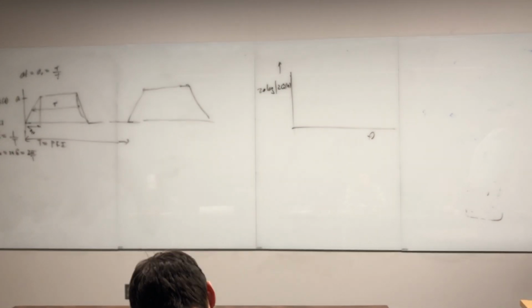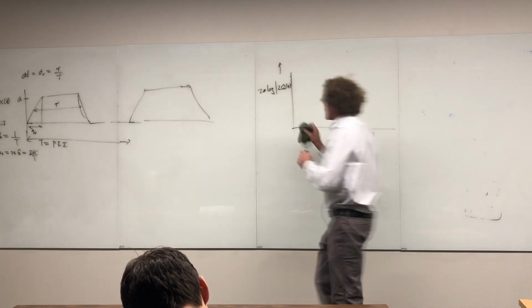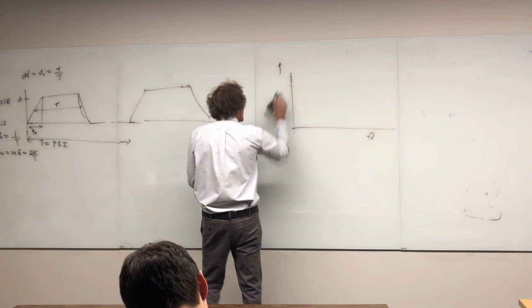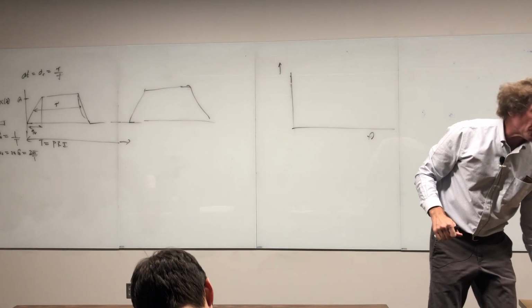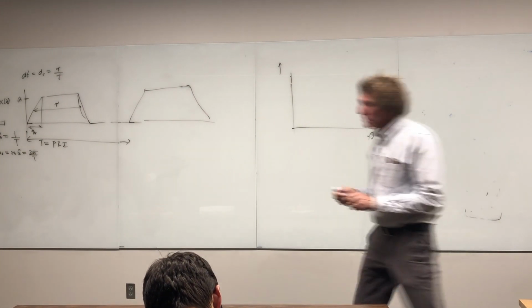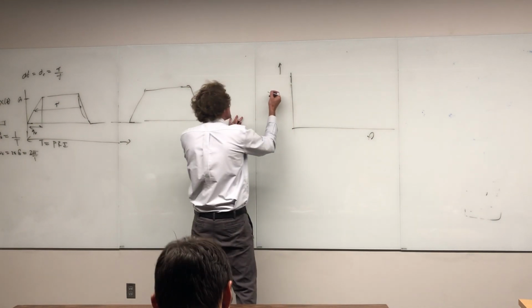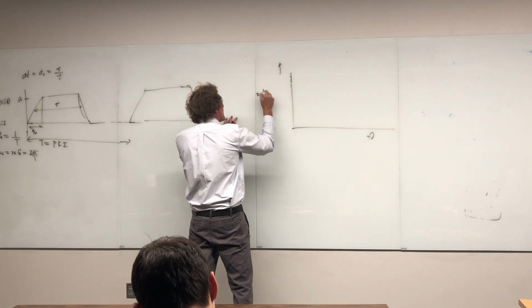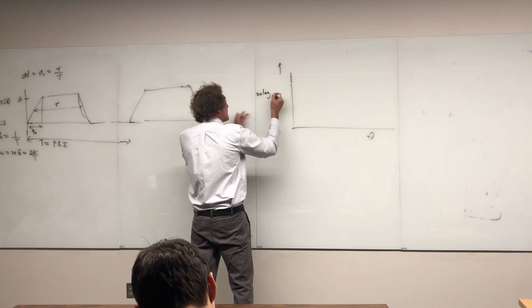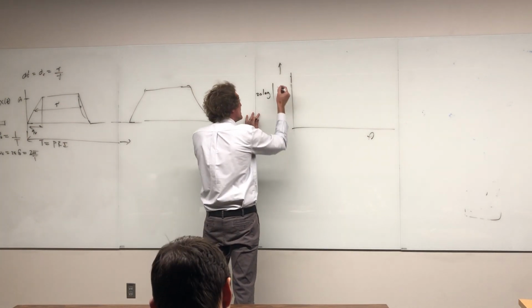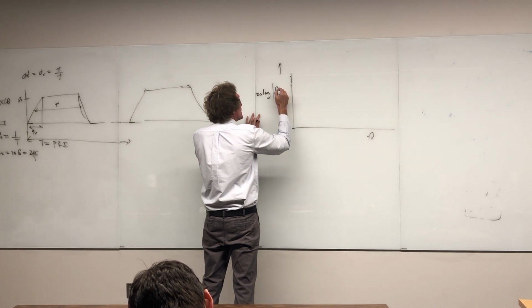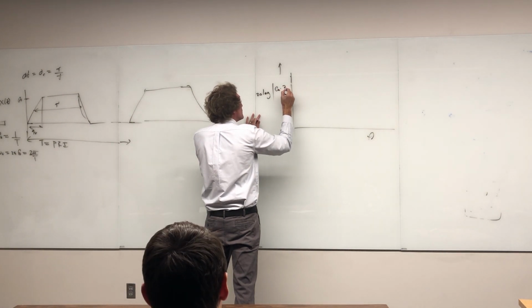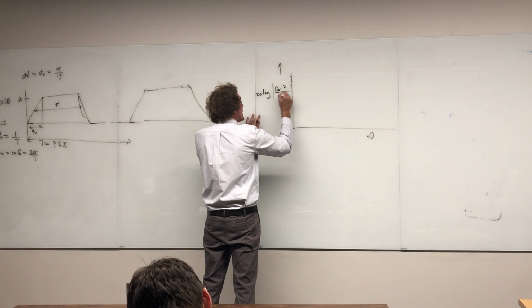I was going to do this in a different way, but let me just say one thing about this. Normally, on that axis, it's dB microvolts or dB microamps, usually. So on this axis, they usually plot 20 times the log of the magnitude of the coefficient C of n, times 2, over 10 to the minus 6.